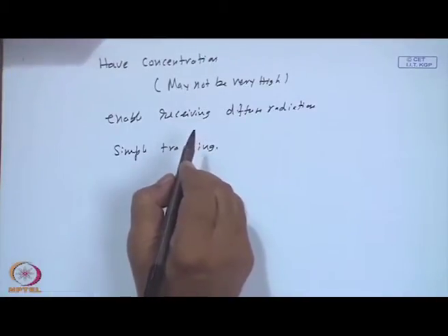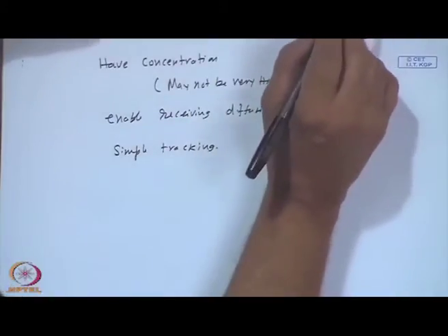You may recall that we discussed 5 cases of tracking, simplest being east-west axis with one single adjustment per day, such that phi minus beta is equal to delta. The next one, that phi minus beta you keep on changing depending upon the time of the day, still the axis being east-west. Of course, the other 3 deal with the north-south axis and a perfect tracker of 2 axes.